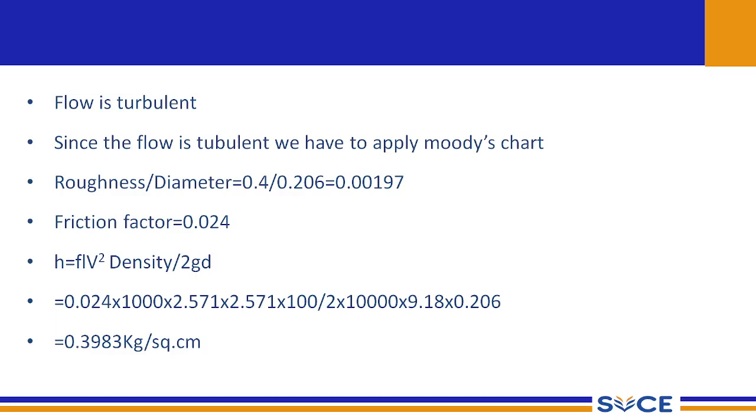So if we have standard diameters available, you calculate the pressure drop for that standard diameter, and then we check whether it is less than the allowable pressure drop. If it is less than the allowable pressure drop, then we can go for the standard size of the pipeline. Considering the schedule number, we need to look at the schedule number to determine the thickness of this line